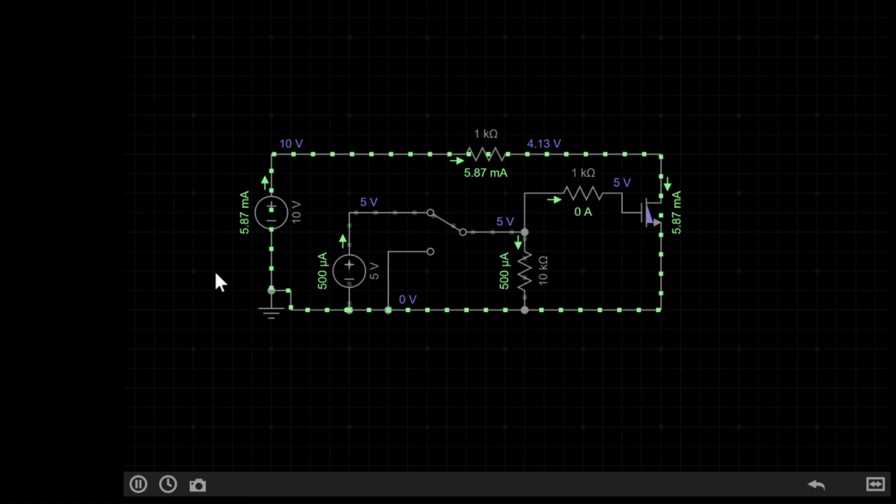Now let's look back at our circuit and go over it with some more detail. This resistor at the top is acting as our circuit's load, so it decides the current that passes through the MOSFET when the MOSFET allows it. This resistor here is a safety feature. Even though by design MOSFETs never allow any current to flow through the gate, sometimes as a MOSFET is switching between on or off, a small amount of current can flow. This resistor here limits that. And then finally, this resistor is what is known as a pull-down resistor, in that it pulls down to ground. This allows the current flowing out of this gate supply to go somewhere.